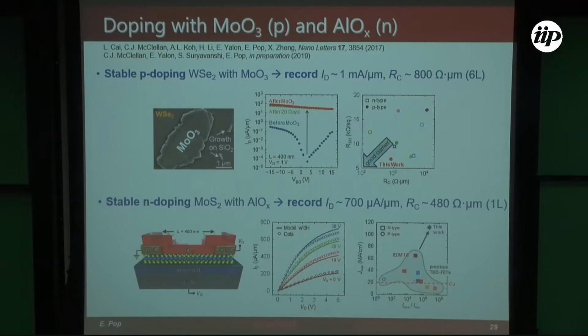And the way we do that is, again, we cap it with aluminum oxide, but it's a funny kind of aluminum oxide. This is non-stoichiometric aluminum oxide. This is not the best quality ALD aluminum oxide we can find. This is deliberately low temperature, slightly oxygen deficient aluminum oxide. And those oxygen deficiencies, it turns out, essentially create certain charge states in the aluminum oxide which transfer electrons to the MoS2. And the MoS2 all of a sudden becomes way more n-type than it originally was.